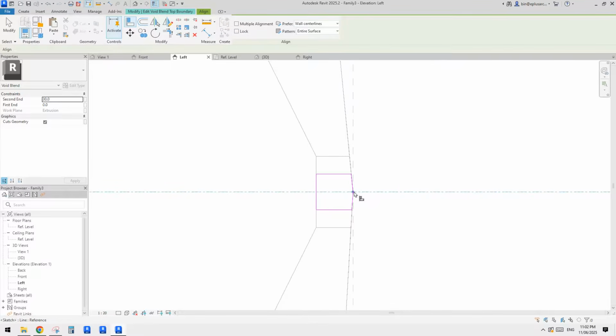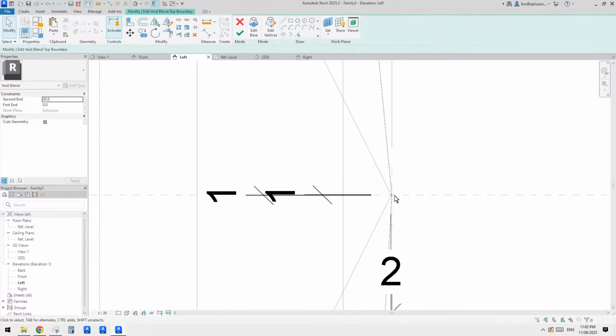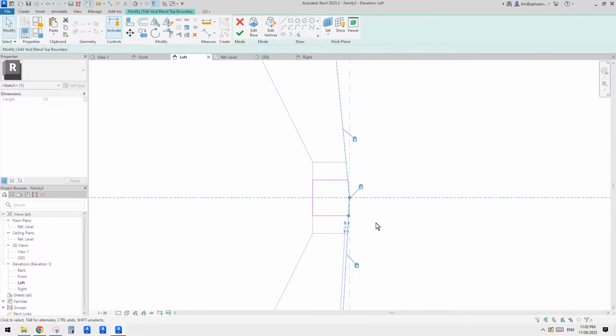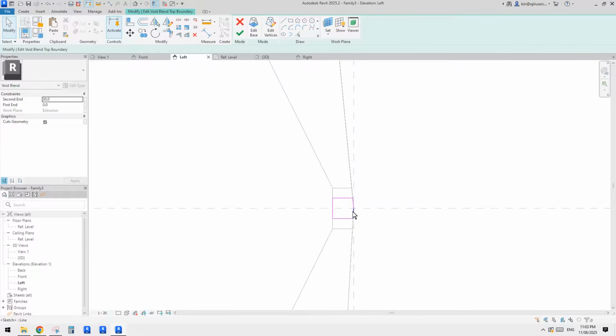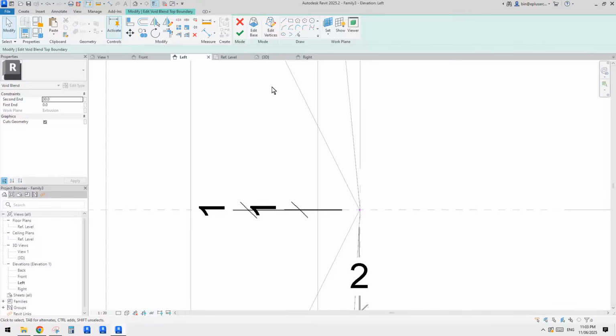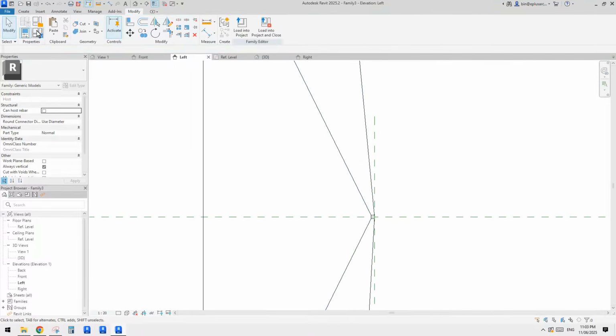Oh yeah, I think it's probably this, because when we change the height of this panel, this reference plane will move up or down depending, and then it breaks. So if we move up and this line becomes shorter, because it's already 1 millimeter, if it's less than 0.8, it will break this. So I guess this is the issue. Now let's try again.